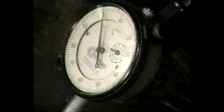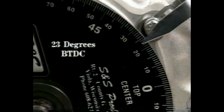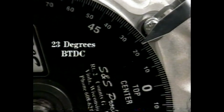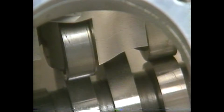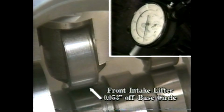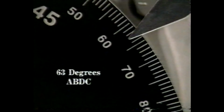We start to rotate the camshaft until the intake lifter has traveled 53 thousandths of an inch up the opening ramp. At this point, we read our degree wheel. Our front intake valve starts to open at 23 degrees before top dead center. Continuing the rotation, we force the front intake lifter up and over the cam lobe onto the closing ramp. We stop rotating immediately when our dial gauge is again at 53 thousandths off the base circle. Our degree wheel now indicates that the closing point of our front intake valve is 63 degrees after bottom dead